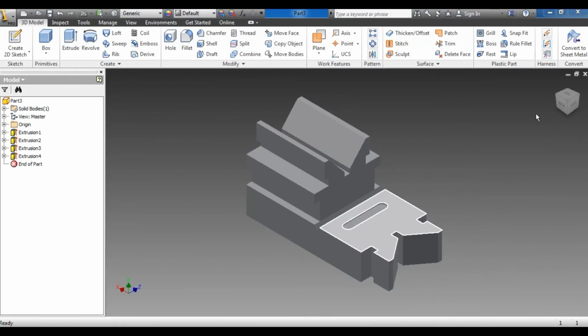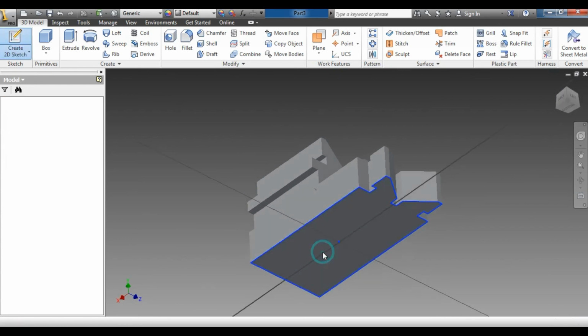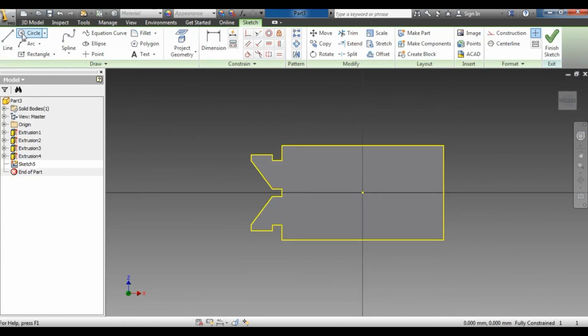So for that one I take the bottom view, the circle dimension is 8 mm as I mentioned, and the distance from here to this one is 25, and obviously this distance from this one up to this one is 24 only because it is a half section.